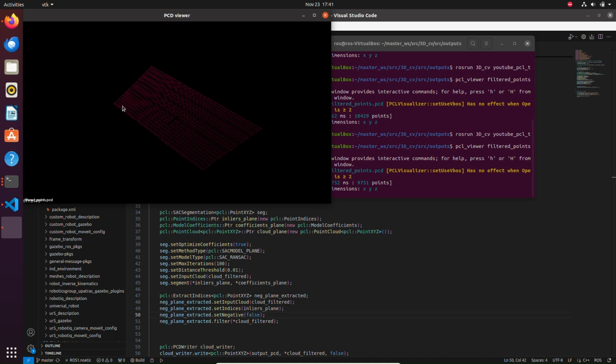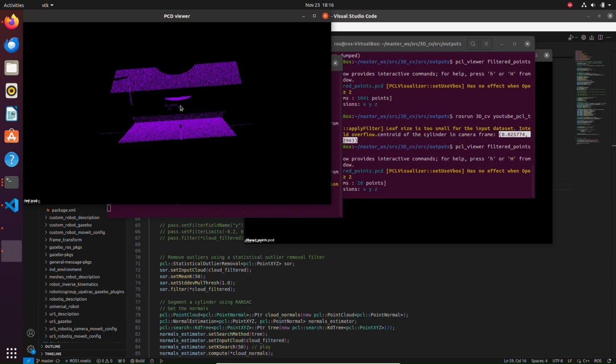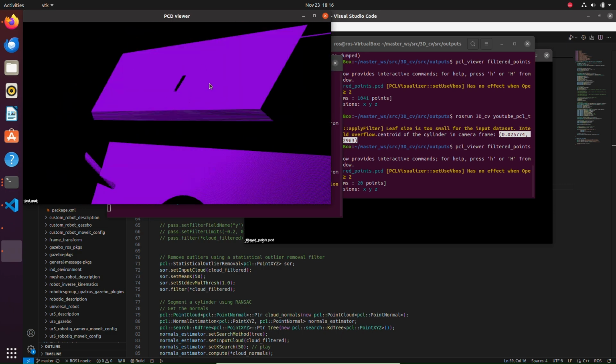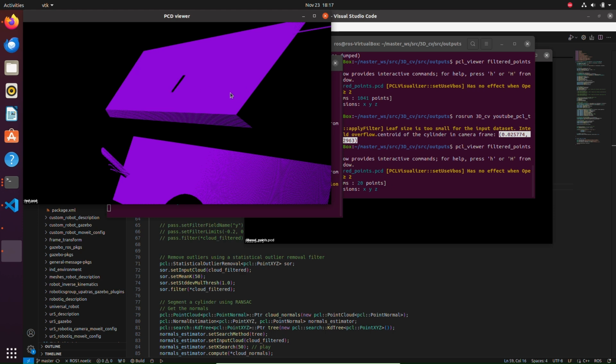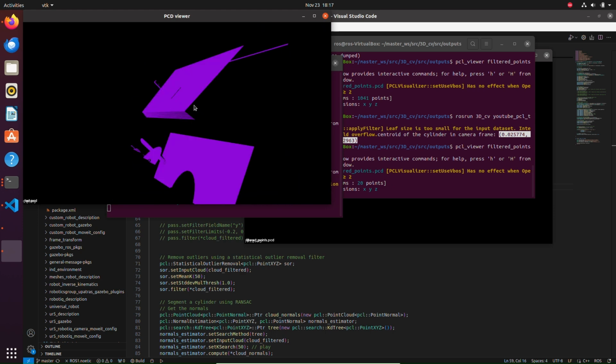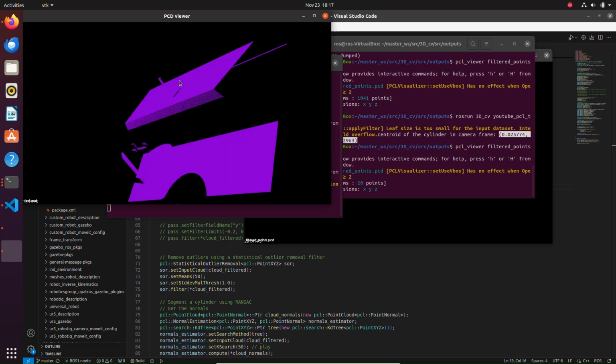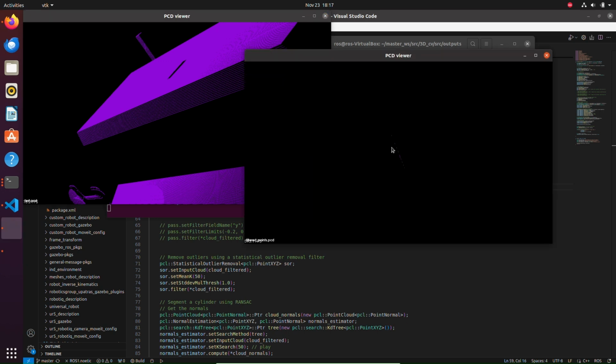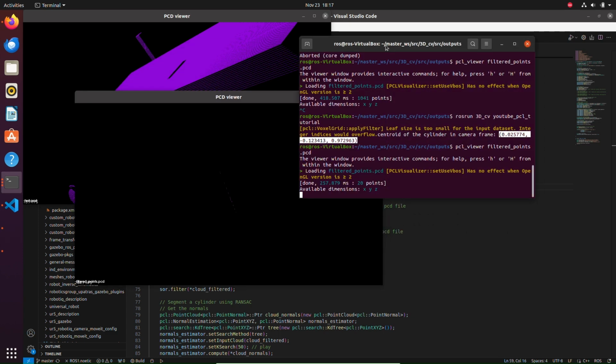This will be very useful to calculate the centroid of the cylinder that we are going to extract, because then we can get the position of the centroid and run industrial applications like pick and place, because we will know the position with respect to the link from which the 3D data is streaming.